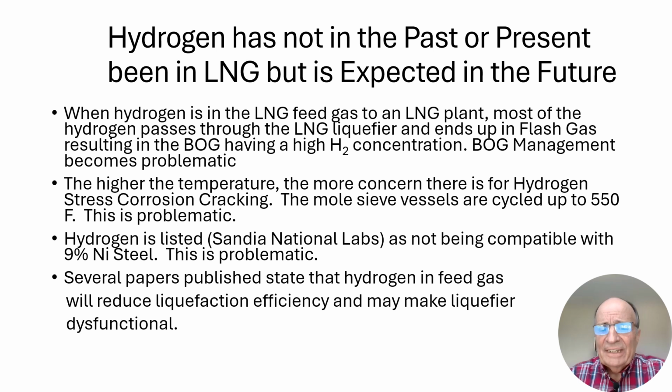So it concentrates more and more. And the hydrogen tends to go where the molecules are the furthest apart. Where are the molecules furthest apart? During the highest stress points of the metal, or the highest tensile stress points in the metal. Hydrogen is listed as not being compatible with 9% nickel steel. That again is problematic because 9% nickel steel is what most of the tanks, LNG tanks, are made of.